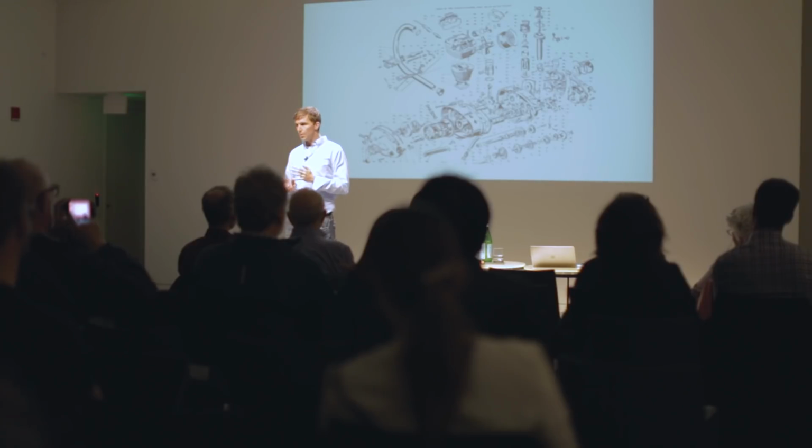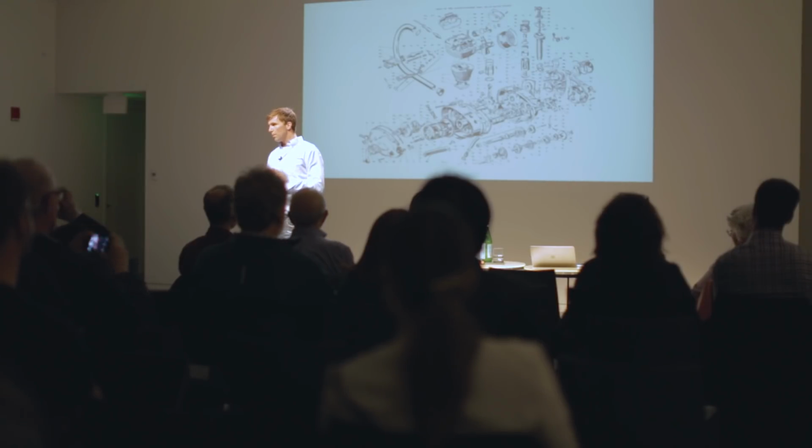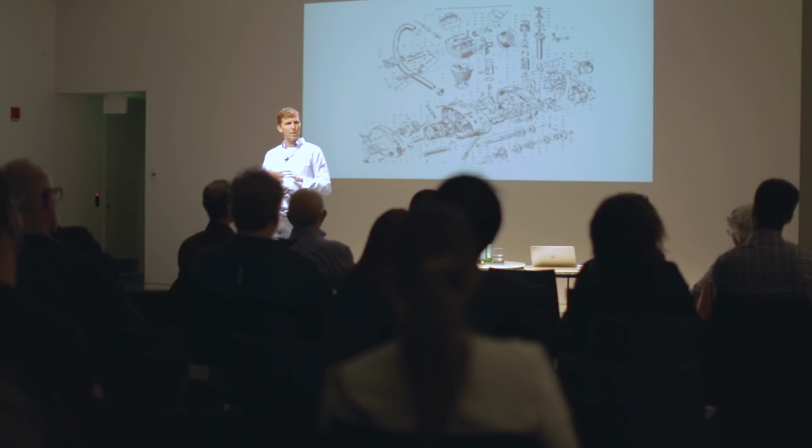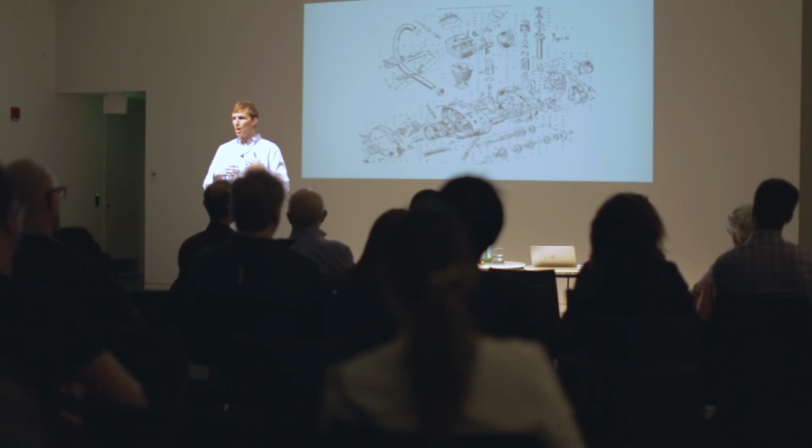It fits the need in terms of the scales that we're interested in, but it limits us in other ways. It limits us in terms of the suite of materials that we can use, and the dimensionality of the structures we can build. 2.5 dimensional maybe we can get out of surface and bulk micromachining processes, but we really want to create rich three-dimensional objects with all sorts of degrees of freedom, articulation, et cetera, as you would have in the organisms that inspire some of this work.